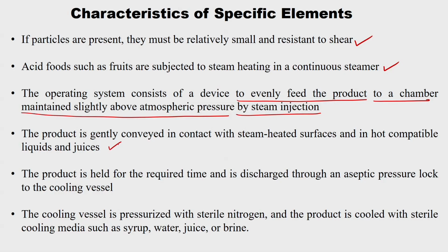So, this may be any heating medium, or if you go to the regeneration section, it is a hot liquid product itself. And the product is held for the required time and is discharged through an aseptic pressure lock mechanism to the cooling vessel. So, this we have seen in one of the lectures.